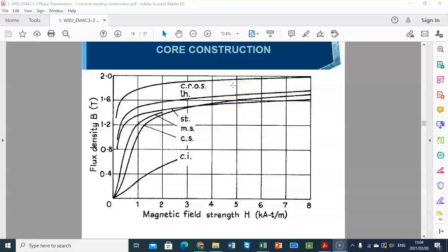And what we can get out of it is going to be losses, and the temperature of the core is going to increase. But we won't get any induction out of that. That's why the efficiency of the transformer would decrease. So what we can see from this BH curve is that we can find the operation point of the steel.